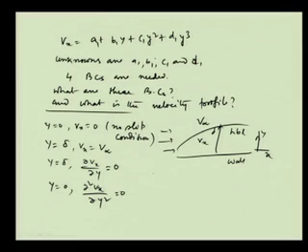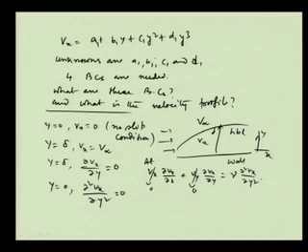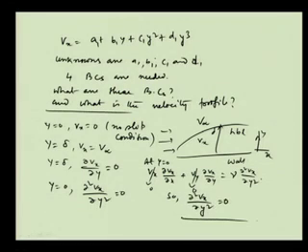We know that if we write the integral momentum equation, that V x del V x by del x plus V y del V x by del y is equal to nu into del square V x by del y square. And what we know is that when y equal to 0, this is equal to 0 and this is equal to 0, both will follow the no slip condition on the plate wall, x direction or y direction, both the velocities should be 0 at y equal to 0. That means del square V x by del y square will be 0. So, this is another condition that we could generate from the continuity equation.